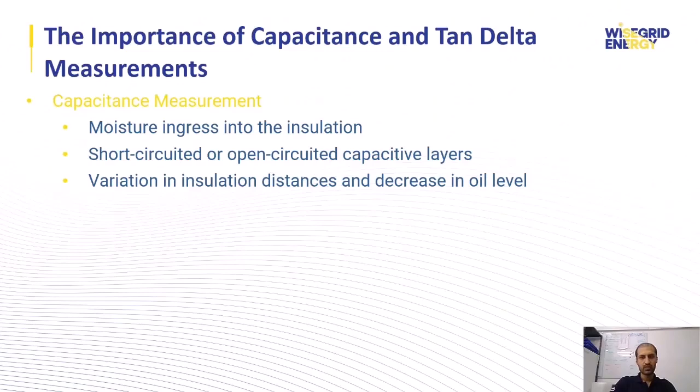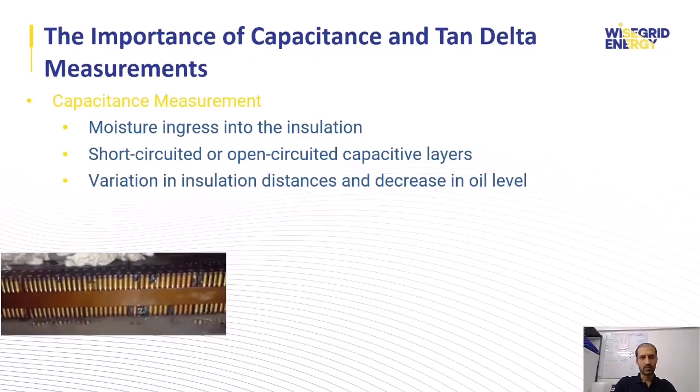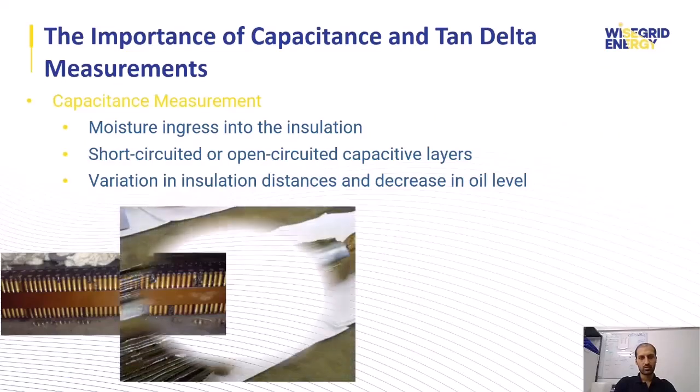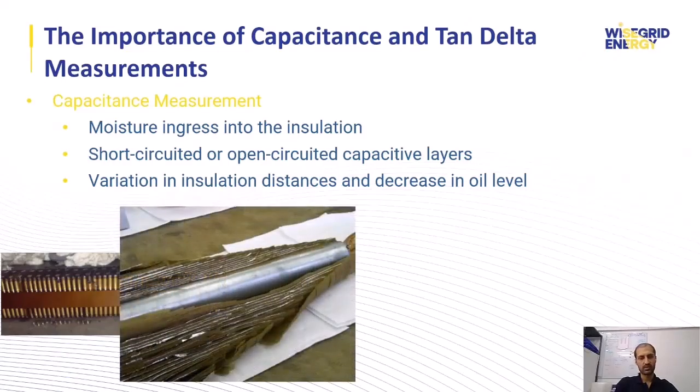Secondly, in equipment like bushings and CVTs, we have some series capacitor layers, and if due to overvoltage in the power grid the total capacitance changes, then under such stresses the capacitance will definitely change because some elements are damaged, and the tan delta value may also shift significantly.